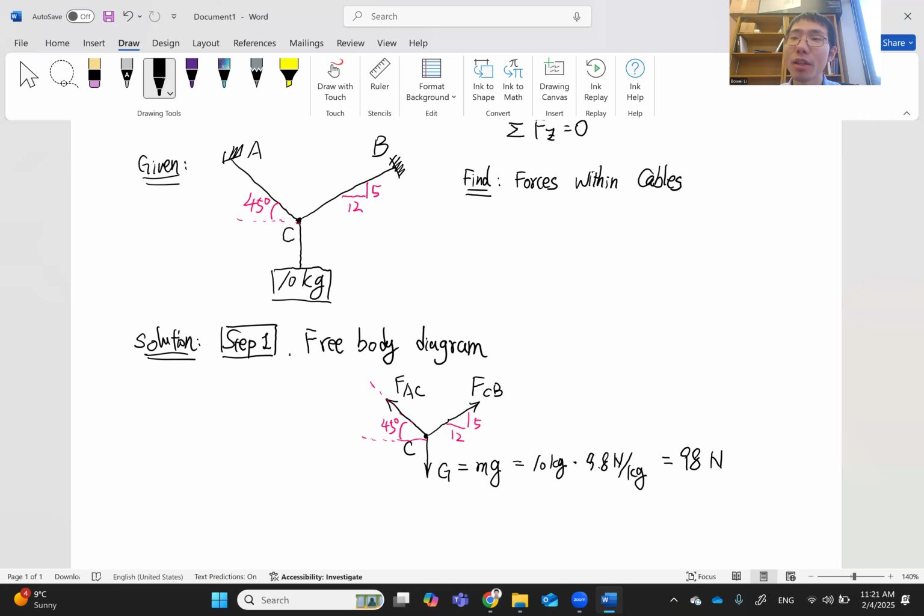As we've been talking about, the free body diagram is a diagram of the part of the object that we're going to analyze and all forces on it. But we didn't talk about which object we're going to analyze. We typically are interested in the object that can involve most of the unknowns of our interest, or most forces of our interest.